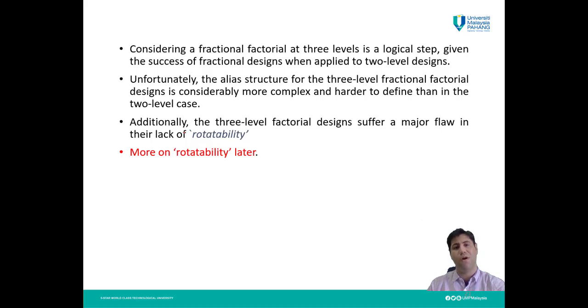But when you don't know, or the number of levels is high, for example, you are going to check a process over a range of temperature, and each 1 degree Celsius is important, between 20 and 60 degrees Celsius you have about 40 different levels. Then instead of a factorial design with a 40-level factor, it is better to use response surface methodology.